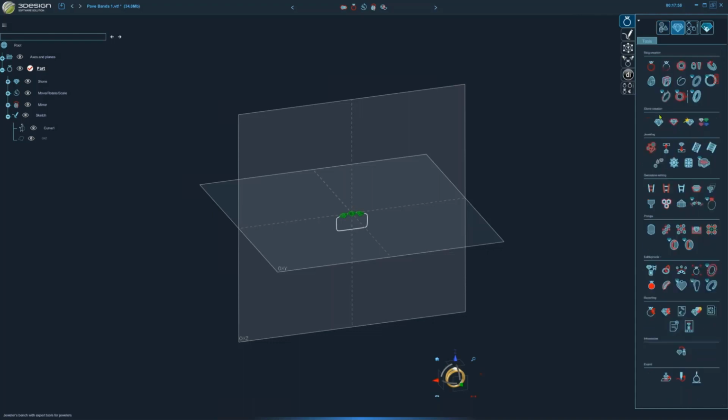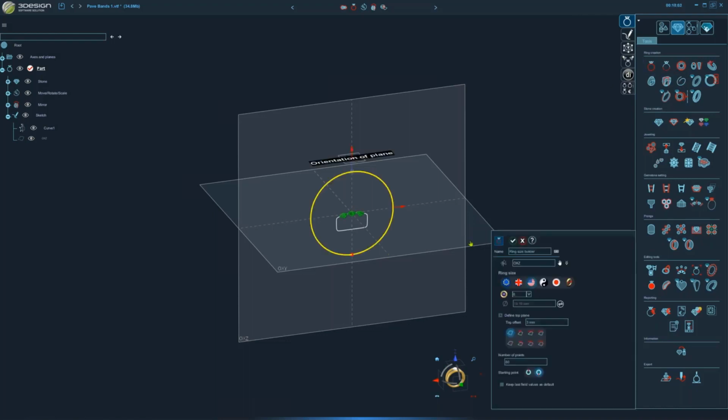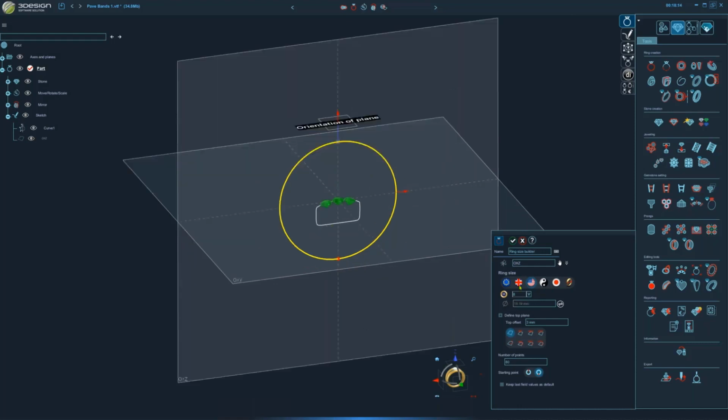And for the ring size, obviously we're going to use a ring size builder that has all the built-in features, so we can parametrically link things to the ring size instead of drawing that in sketch mode where we know it's not going to be linked to anything. So this tool is going to help a lot with that. And we choose our finger size. I'm going to start with a size 8. It's a nice medium size to start from.